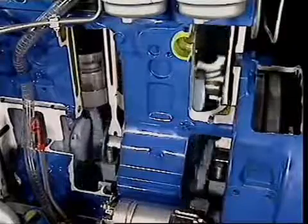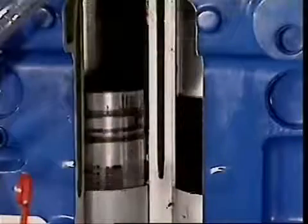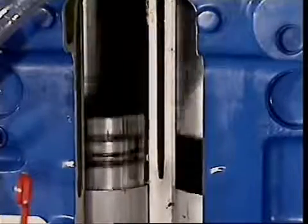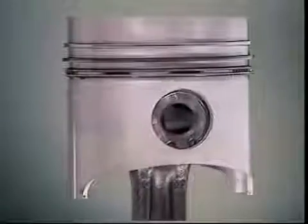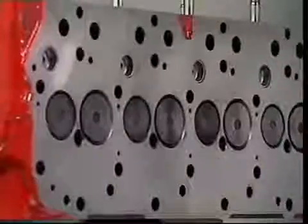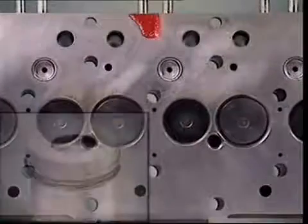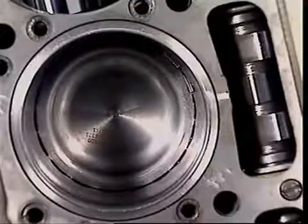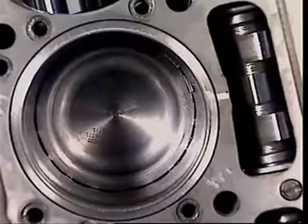A connecting rod links the crankshaft to the piston. Pistons in 2- and 4-stroke diesel engines can change directions hundreds of times a second and are exposed to extremes of heat and pressure. Modern pistons are made of aluminium alloys. Diesels using direct injection have an almost flat surface on the cylinder head, and almost all of the combustion chamber is in the head of the piston. Engines with indirect injection usually have pistons with a flatter head and sometimes with small indentations.